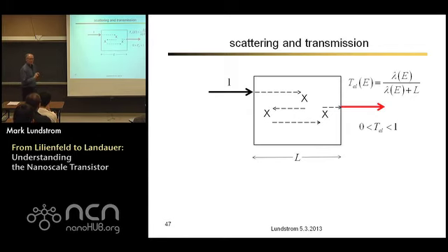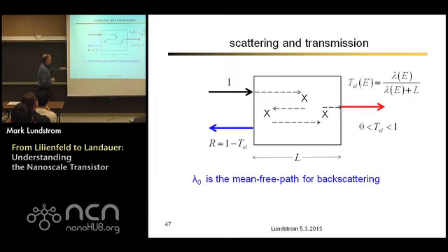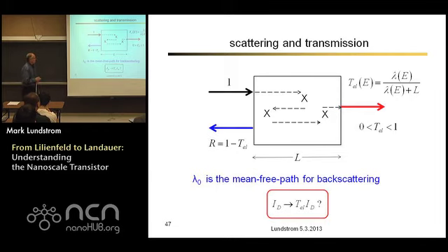All right. It's actually better than that. It's not just an empirical ad hoc thing. You can actually derive it, and it works really well in practice. Okay. So this critical parameter is the average distance between scattering events. Okay, so we want to get this in our theory so that we can treat MOSFETs that operate when there's a little bit of scattering.